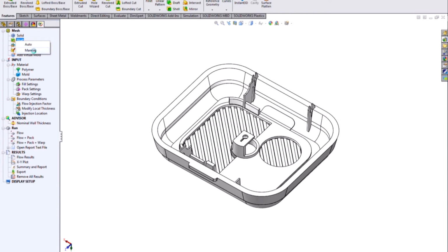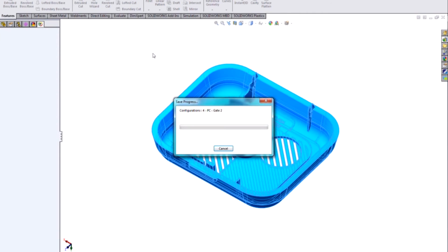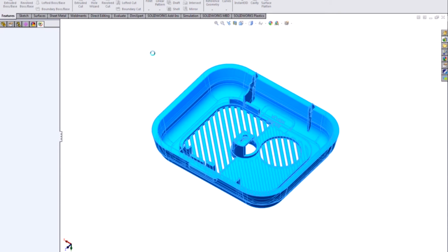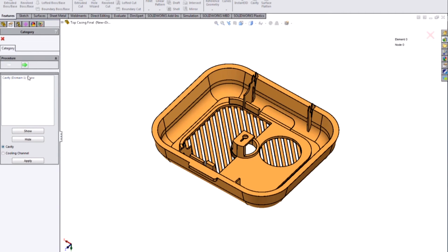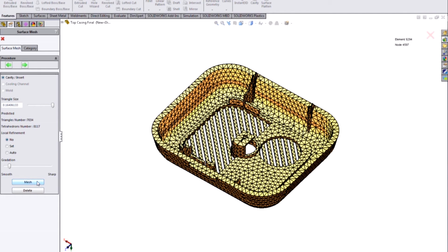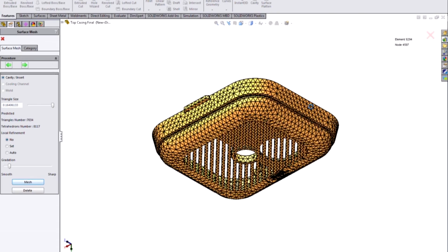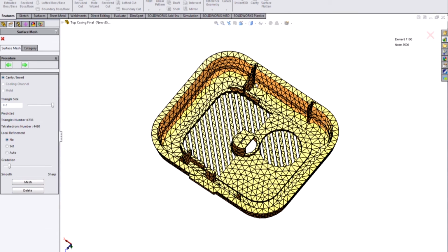I start off by defining a mesh grid. The process to put together a mesh is really the only analysis-specific thing that we need to do. But we have to turn this 3D shape into a grid that the software can analyze. So typically what we do is set some sort of size, right? And we can tell the software to go mesh that. Very fast, automatic mesh tools. Just go a bit bigger. I've got a fairly coarse mesh that I'm starting with here.